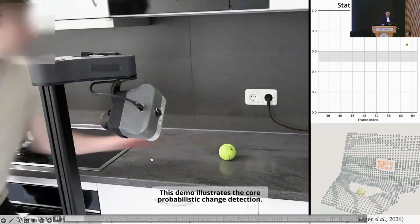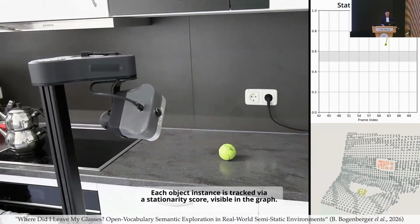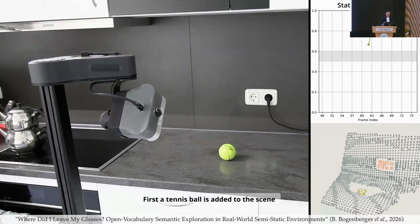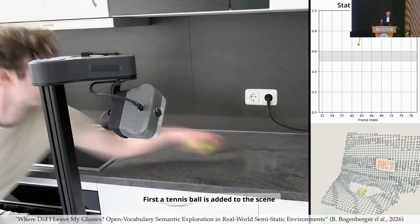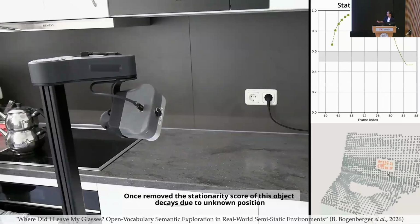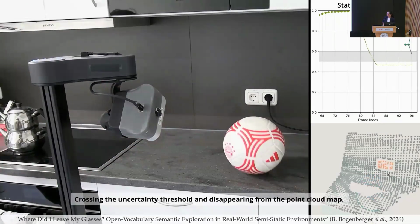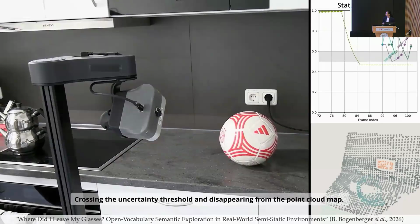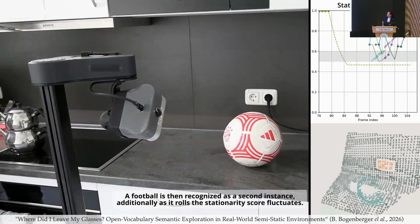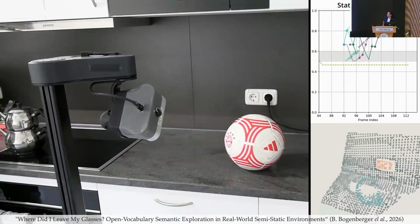If we have a ball here, the top right corner shows the stationarity score estimates. Once the object is stationary, this will converge to 1. And if we remove it, this will drop below the threshold, and if you see the map down there, the point cloud gets removed. And if we introduce another ball, this again is introduced to the map with the corresponding stationarity score being tracked over time.